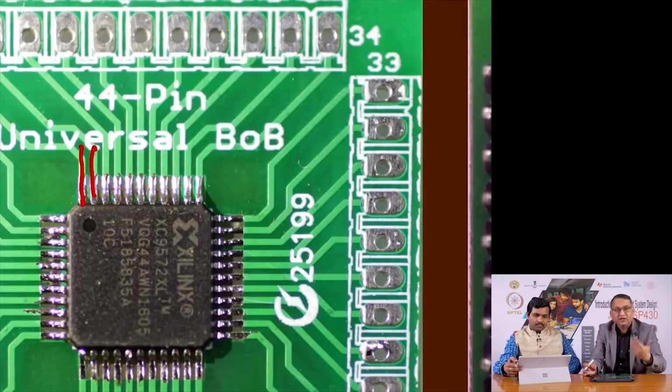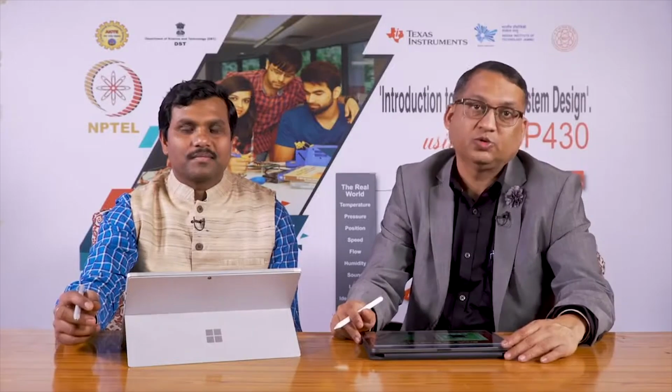Increasingly, the integrated circuits available these days are being made available only in SMD versions, and therefore it raises a very important question: how could we prototype using the zero board technique with circuit components which are primarily surface mount devices? The solution is to use what is called a breakout board.